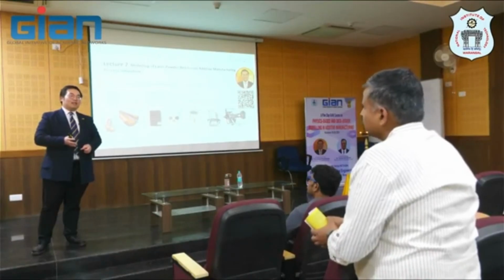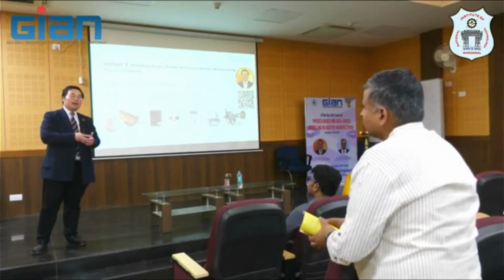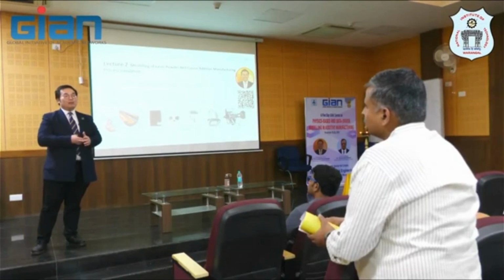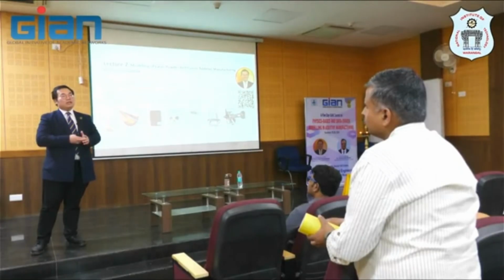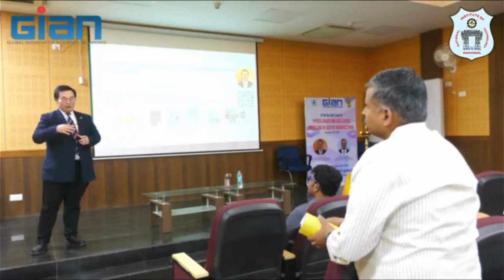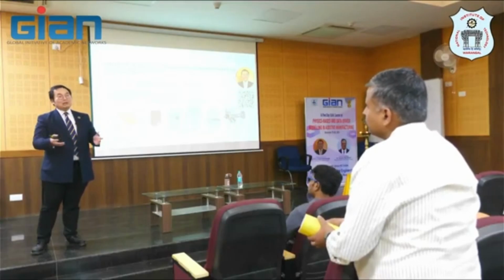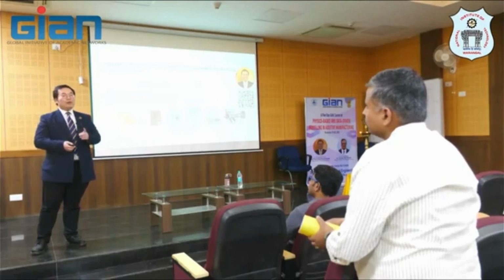They can innovate this because they understand what's happening during LPBF and electron beam melting. There are some differences which they can leverage. But if you can understand the thermal signature, as we call it, of the process, you may be able to design somehow the gradient similar to the casting situation. And then hopefully you can grow only 1 grain.